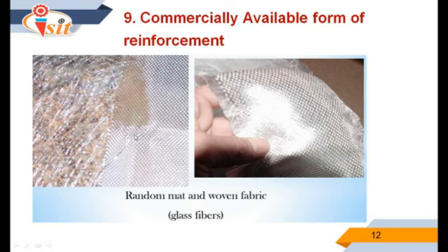The glass fibers over here are quite whitish in nature, and when we are using such mats or woven fabrics, we have to take care that we cannot handle the glass fiber directly without any gloves, because the glass particles may penetrate your hands, and later such an itching may happen when you are going for the real application.